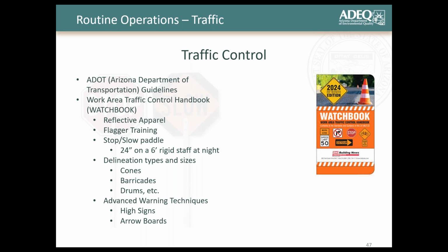Both the Arizona Department of Transportation guidelines and your handbook are going to help you define proper delineation types and sizes: cones, barricades, drums, what's appropriate for the type of traffic control, whether it's temporary or long-term. Then, of course, advanced warning techniques with your high signs and arrow boards.